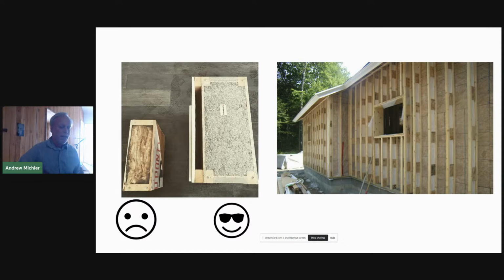It's protected on the inside. As you can see, there's a little gap between the drywall and where the insulation starts, and that's our air barrier, and where we can run power systems like that. There's all sorts of ways to design these passive house walls, so we don't try to get too prescriptive in that sense. But at the same time, what we're looking for are these standard conditions for how the wall is going to perform.